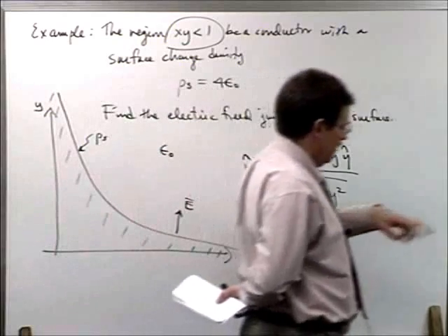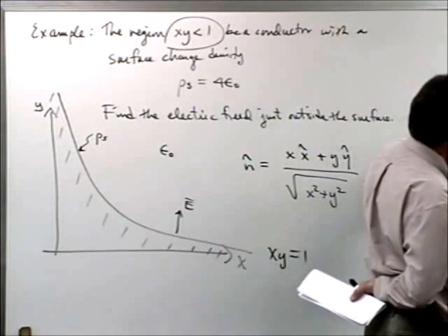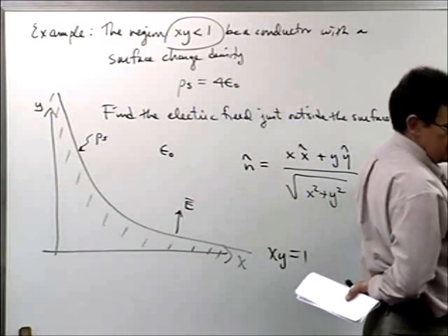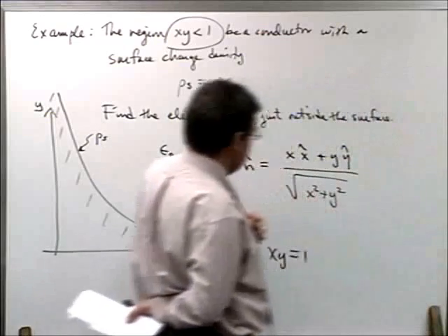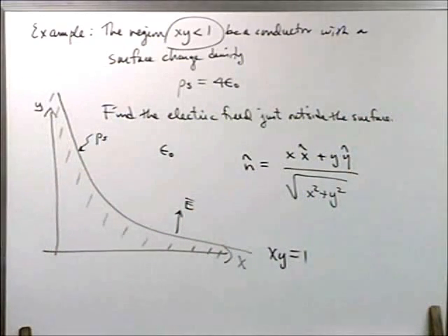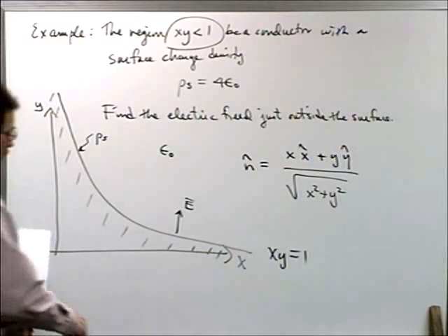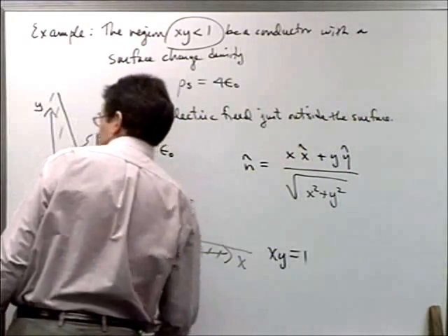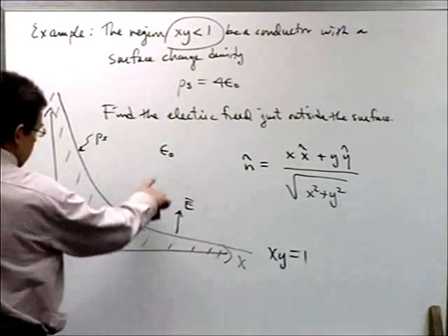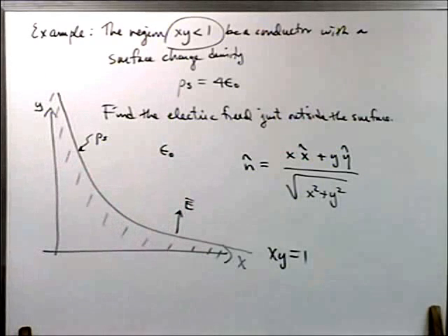And the normal component then, since we're by a conductor, we would use this equation here that says n dot epsilon E is equal to rho sub s. Okay. So in this case, we've got an E field that's pointing in the normal direction.